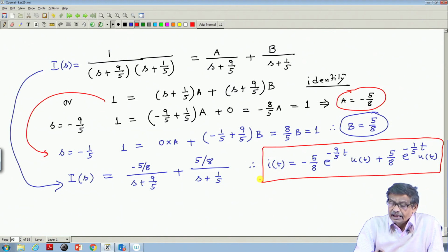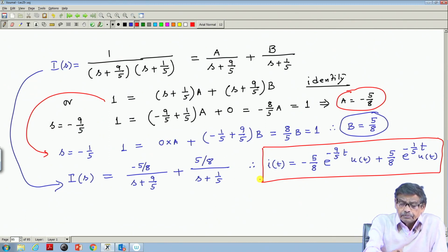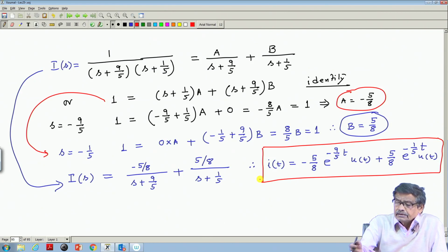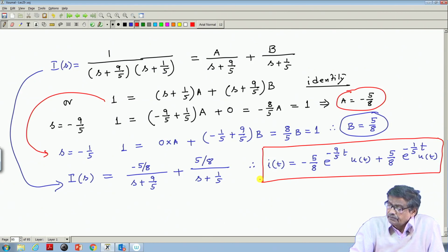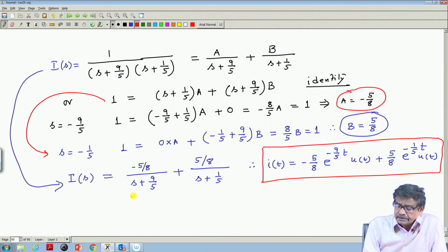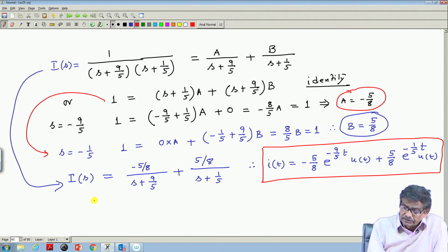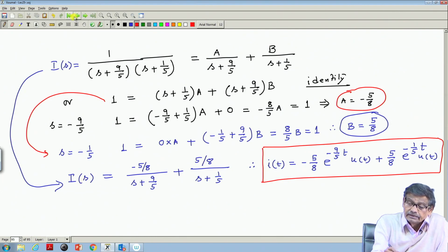So, I dealt with only algebraic equations, then expressed the variable I want to get in terms of the S domain, and then expanded it in partial fractions and tried to identify the terms. While taking the inverse I did not apply any formula, just some standard tables, and I got the result. Now, my next thing was what was VC(s).